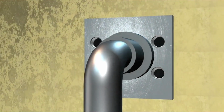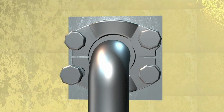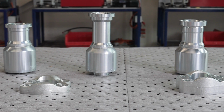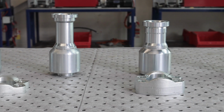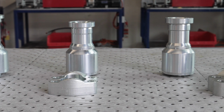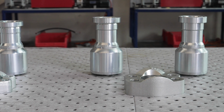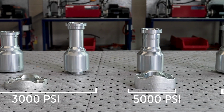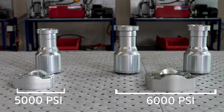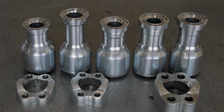Let us have a look at a common hose connection system often used on plant and mobile equipment. This is sometimes referred to as 4-bolt flange, with several standards and designs being supplied to the market. For comparison purposes, we've selected a range of 1.5-inch hose tails including Code 61, Code 62, Letourneau, Komatsu and Supercat. These hose tails are generally rated between 3,000 and 6,000 psi.